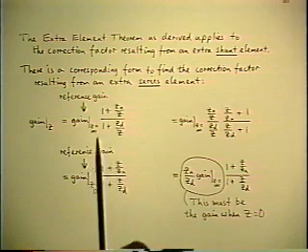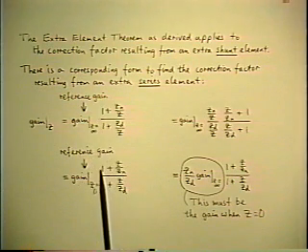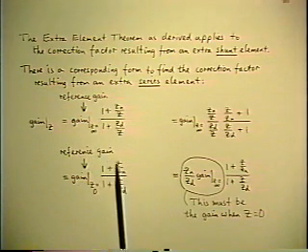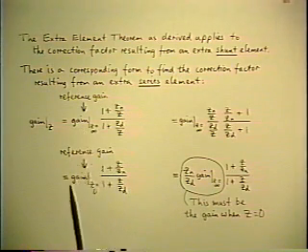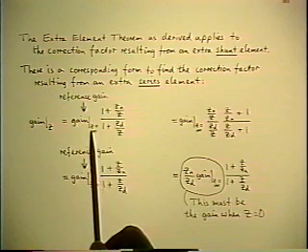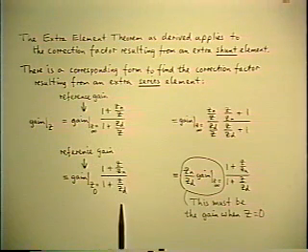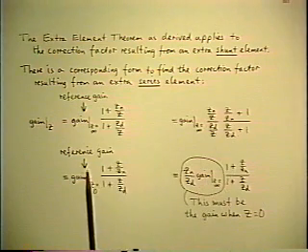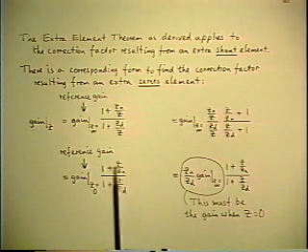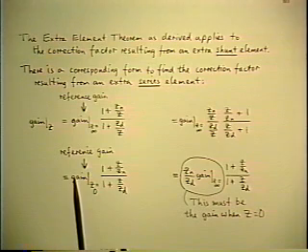And I pointed out at the time that this was a direct analogy with frequency response. You could either use the zero frequency gain as reference or the infinite frequency gain as reference, and you have either a normal pole and zero or an inverted pole and zero. This is exactly the same thing, except the variable is impedance instead of frequency.